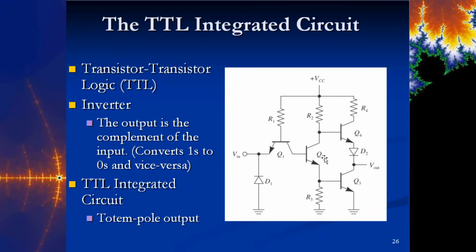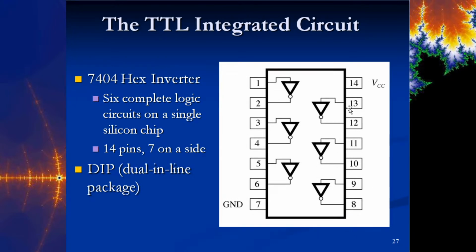So, digital is something we're superimposing on analog systems, if you will. Okay? And so this is what it looks like inside that IC chip. Between pins 1 and 2, I can put my input in through 1. Those internal transistors will convert that into a 0. Or if I put a 0 on the input here, it'll convert it into a 1. Okay? And I've got 1, 2, 3, 4, 5, 6 of those available on one chip. Okay, so that's pretty powerful.